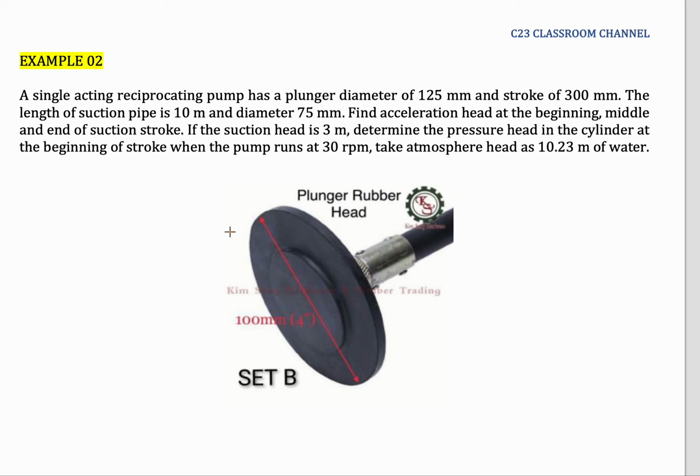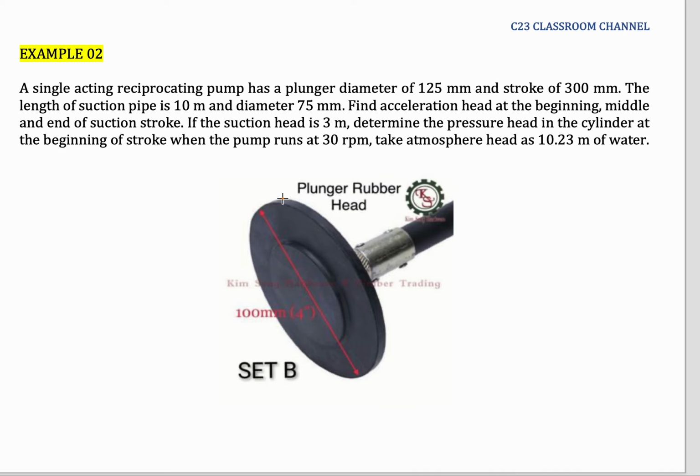So this is a reciprocating pump, but it does not use a piston. Normally a piston is a metal iron casting shape, or iron casting parts, the same as the piston in an engine. That's the basic idea of a piston. But the plunger here is something like this, and sometimes it's fabricated from plastic or soft rubber or hard rubber, something like that. Why do we use rubber? Because we want to make sure that they are very tight at the gaps between the cylinder at the edge of the disc here.